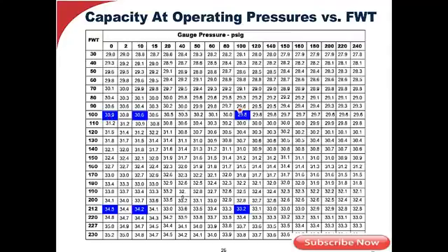If I go to 100 pounds of operating pressure, and I'm at 212 degree feed water, I've lost a little bit, 34.5 to 33.2 because of the operating pressure increase, more BTUs required for sensible energy to get that temperature up so I can start to apply my latent energy.